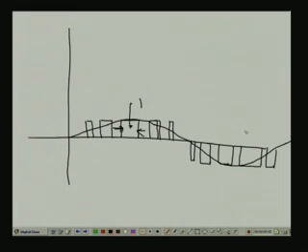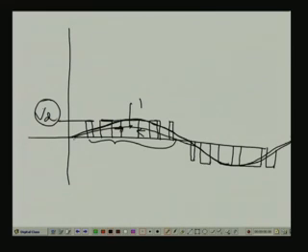In the switched wave the heights remain the same, this is again Vd, but if the pulse widths are varied, then the amplitude of the fundamental will depend on these pulse widths. So by having these pulse widths, you can make the amplitude like this, or like this, by just varying the pulse widths. Although the height does not vary, the effective amplitude of the fundamental will change.